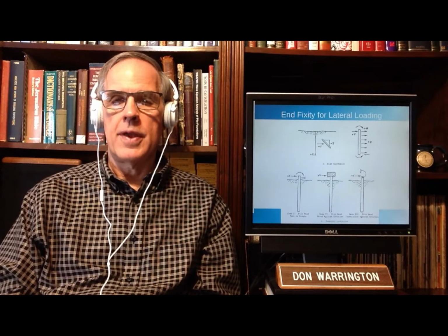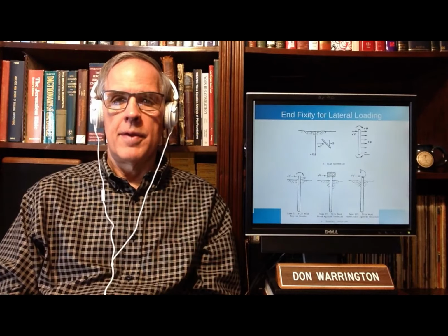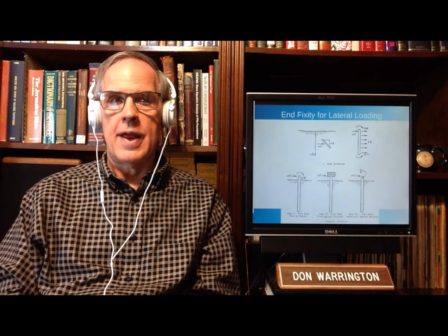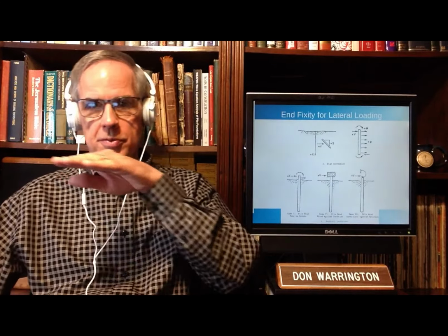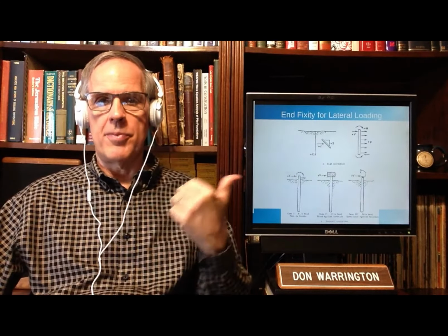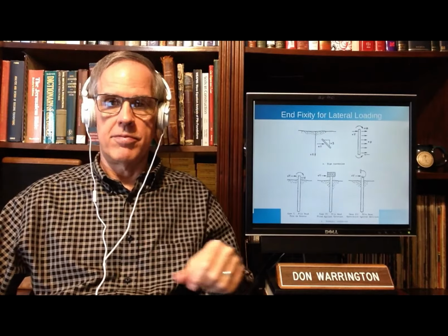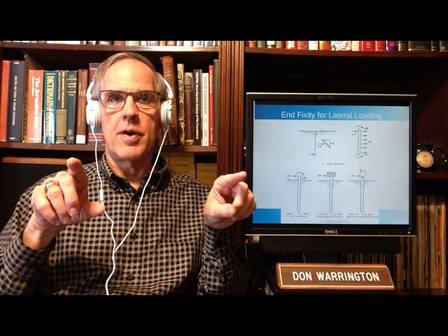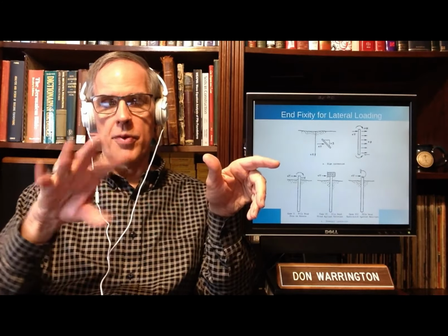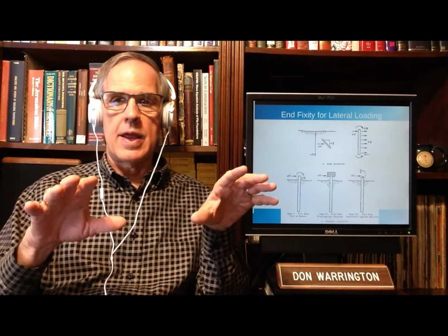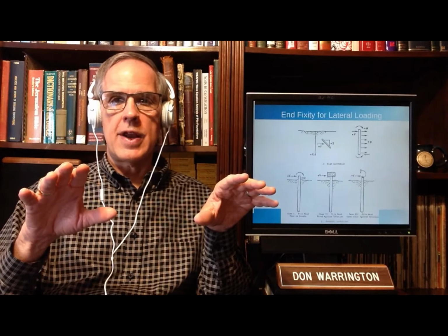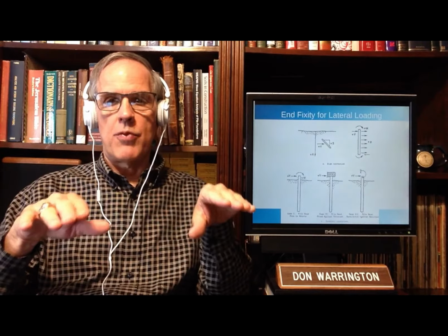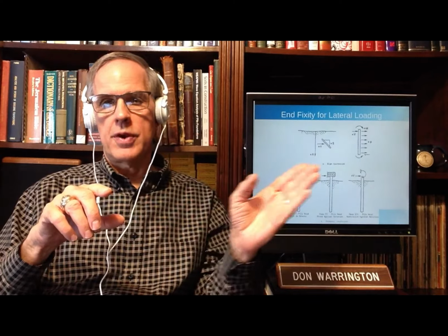For example, a simply supported beam, in order to be simply supported and statically determinate, can have, and I'm going to assume we're talking about a horizontal beam because I know I'm sitting here looking at a vertical one, at each individual point, as long as the 2 points can rotate in both ways, we constrain any movement in this direction, and only on one do we constrain movement in this direction.